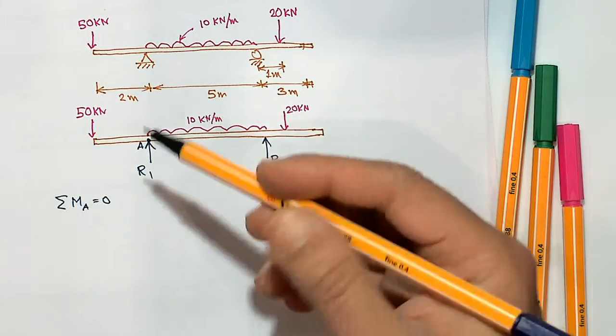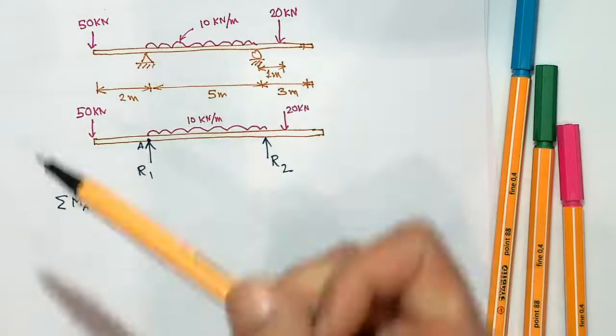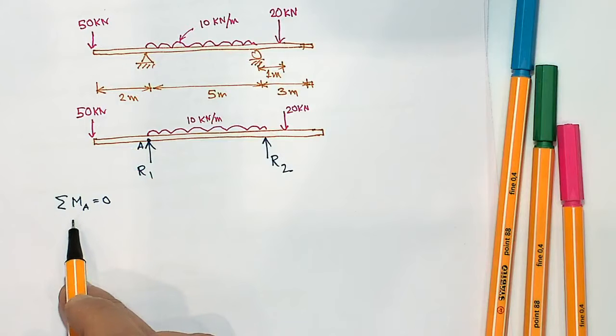So doing this moment equilibrium equation, I can choose a sign convention which is either clockwise moment or anti-clockwise moment is positive. It is not the bending moment sign convention. You must make sure that hogging moment positive or sagging moment positive are primarily for the bending moment sign convention because they come in pair, left side and the right side of a cross section.